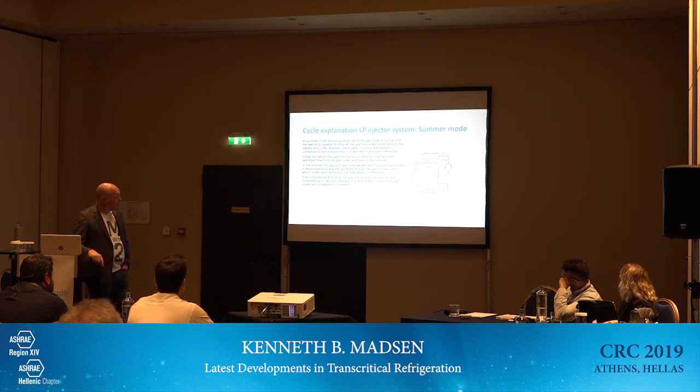And then it's lifting the flow from the evaporators through the ejector to the receiver, where the compressor, and now we don't have a parallel compressor anymore, now we only have a medium temperature compressor that is basically running as a parallel compressor here, you can see. But that means we do not need two suction groups, we do not need extra controls for parallel compression. At the end of the day, the system here is actually a lot simpler than the system with parallel compression.